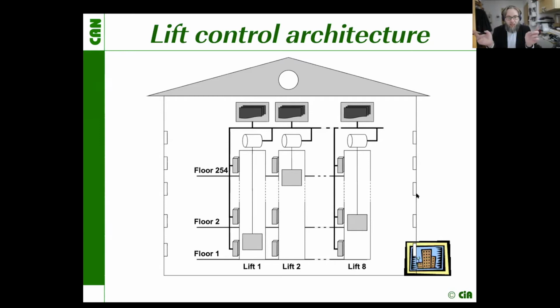The cable length limitation depends on the speed. In case of Lift applications, the speed is defined as 250 kilobit per second, and that roughly translates into a network length of about 250 meters.